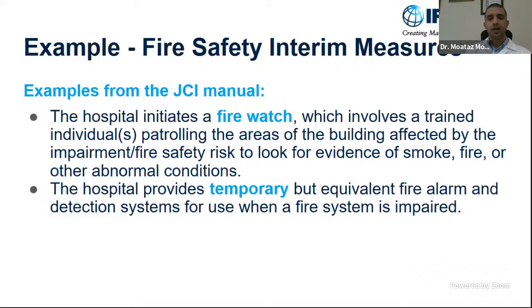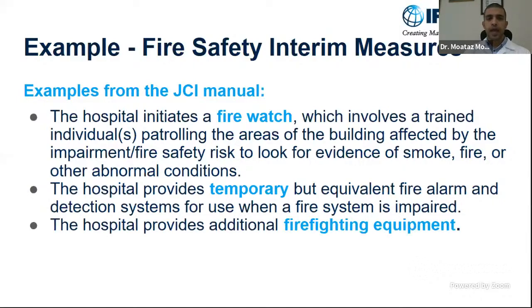Another interim measure includes providing a temporary but equivalent fire alarm system for use when your fire system is impaired in a section or an area in your hospital. And of course, whenever your system is compromised, you should consider adding additional manual firefighting equipment and training your staff to use them.